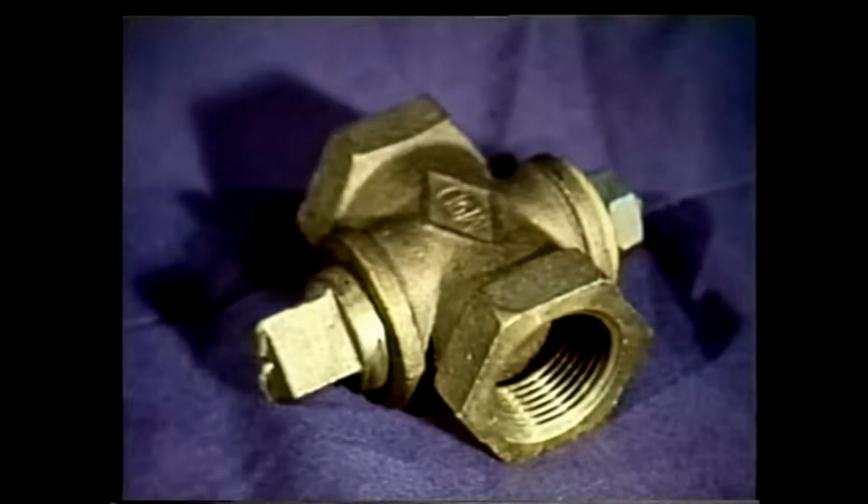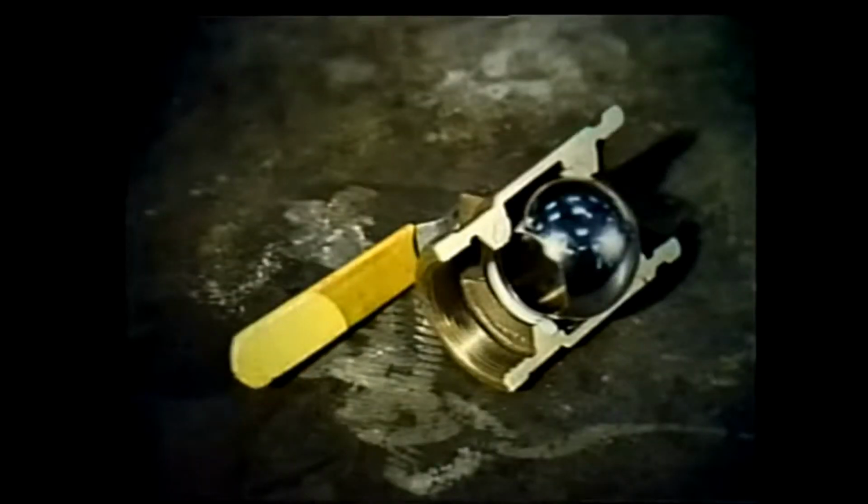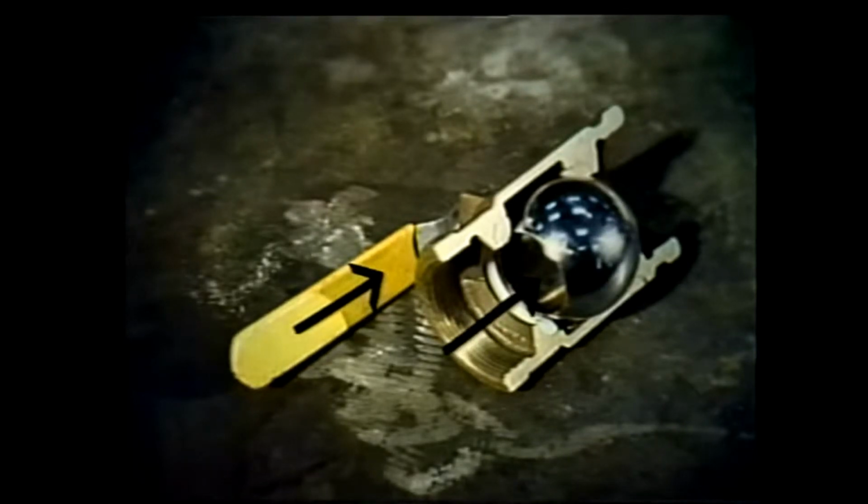The plug valve is very adaptable to systems carrying slurry. Slurry is a fluid often containing large particles. Often the valve will indicate which way the flow is going. For instance, on duplex strainers, the handle will point to the strainer with the flow through it. In a regular on-off ball or plug valve, the handle is usually in line with the post. So if the handle is lined up with the pipe, there will be flow through it.